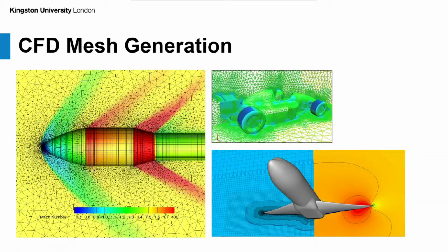If you go with a much finer mesh, the result we get is quite close to the actual result we expect once we run the actual experiment. But again, it's time consuming. On the other side, if you go with a not really dense and not accurate mesh, it is faster. But the result might differ a little. Usually the difference is around 10 to 20%. Of course, the main goal of CFD is to get close to 1 to 5% tolerance with the actual experiments that you do.